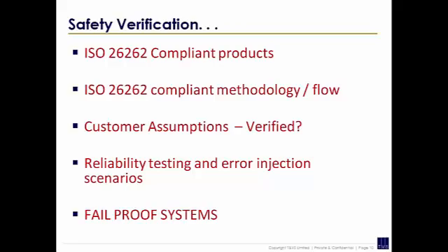And reliability testing and error injection. This is taking an important role. There is something called RAS, which is actually a software topic basically: reliability, availability, and serviceability. This is very dominant in mainframes and servers, where we challenge zero downtime and a server will run for hundreds of years without rebooting. We thought such scenarios would only be restricted to processors and servers, but SoCs in some terms also need error injection scenarios and correction.